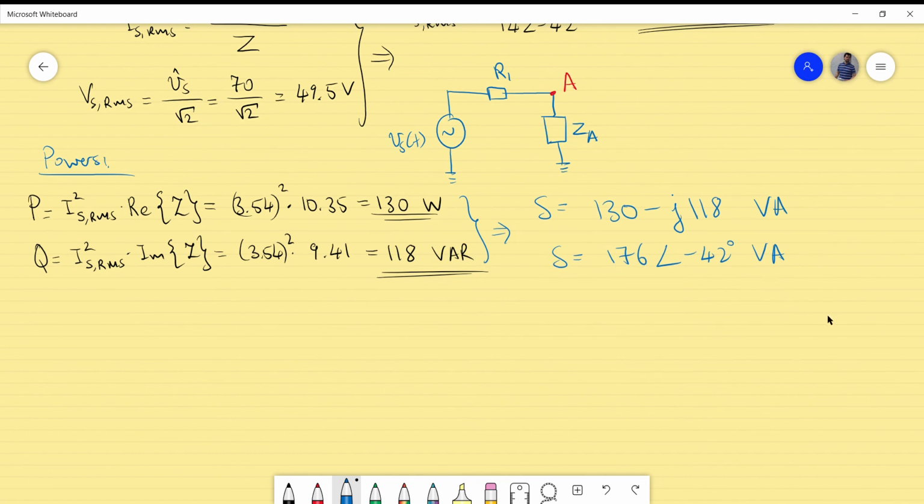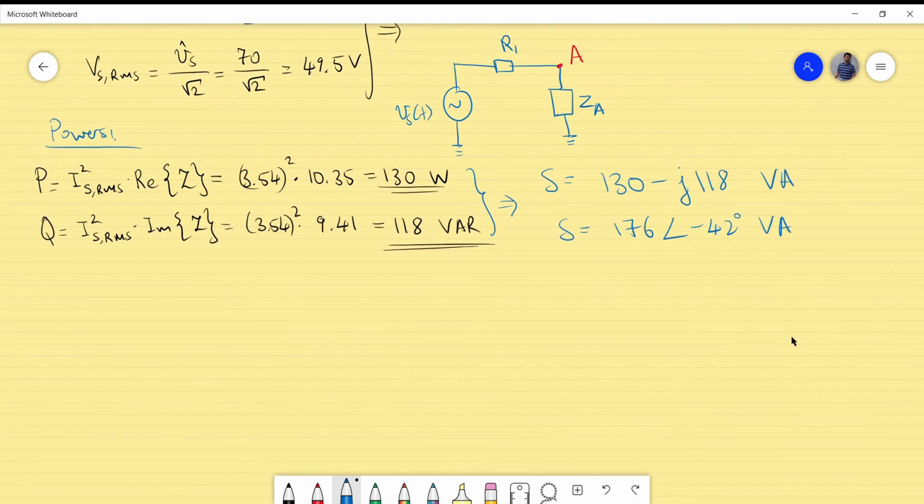Now the final situation is actually the calculation of the power factor. So the power factor, that's the last one, the power factor, which is leading, we already know. So power factor PF, which is the cosine of theta, and which is leading, because the current has a positive phase.